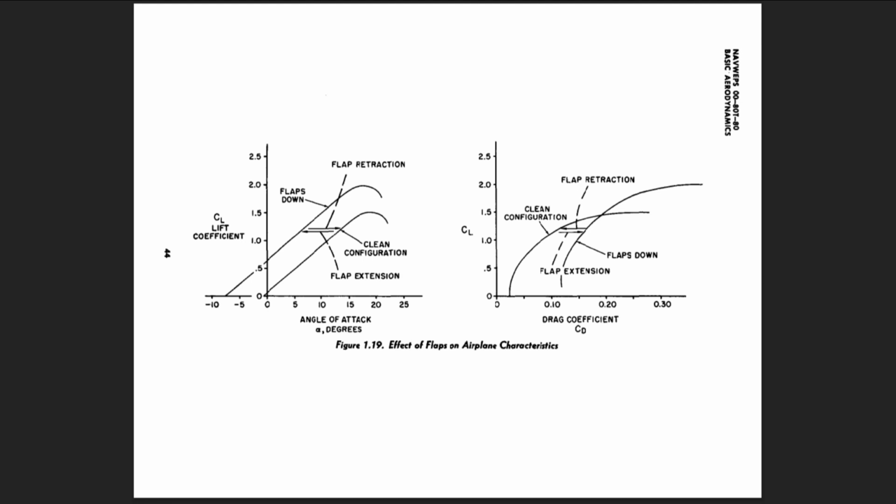1. The reduction in camber by flap retraction changes the wing pitching moment and, for the majority of airplanes, requires retrimming to balance the nose-up moment change. Some airplanes feature automatic retrimming, which is programmed with flap deflection. 2. The retraction of flaps shown on Figure 1.19 causes a reduction of drag coefficient at that lift coefficient. This drag reduction improves the acceleration of the airplane.